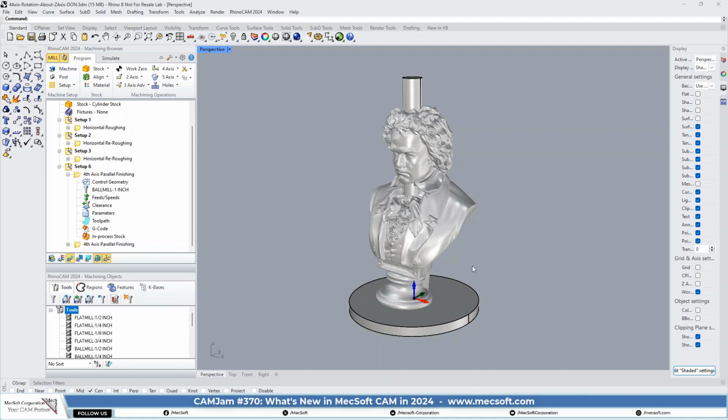Well, Don, that's partially correct what you're saying. There's one way you could have done it. You could have used setups and rotated the setup where the X and or the Y axis is pointing in the Z-axis. Yeah. But the problem with that, the transformations were being computed like you had a 5-axis machine. So we have actually fixed it, and you don't really need to use a setup. And then we had 4-axis users who did not have multiple setups in the configuration, so they wanted this option. So we introduced this option.